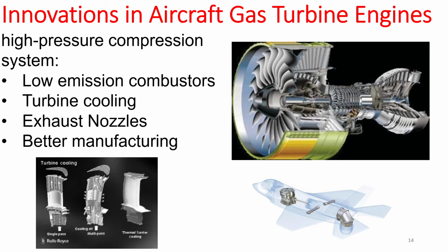the other innovations happen in the combustors, like the environmentally friendly, low emission combustors, or more efficient combustors in general. Turbine cooling, as I mentioned, is a very important part of the process. You want to keep your turbine healthy, essentially. You want it to run as much as possible. And playing with the exhaust nozzles, that started from World War II again. Most of these things, most of the propulsion age started from World War II. So that's something to keep in mind.